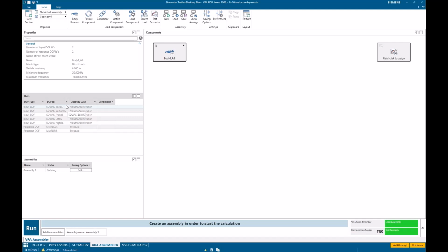So I have 5, technically 10 FRFs here. They're P over Qs, where I've set a Q source at each of these EDU locations that I've measured the pressure response inside this body, or I simulated those same scenarios. But that's what this body is, just a collection of those transfer functions.